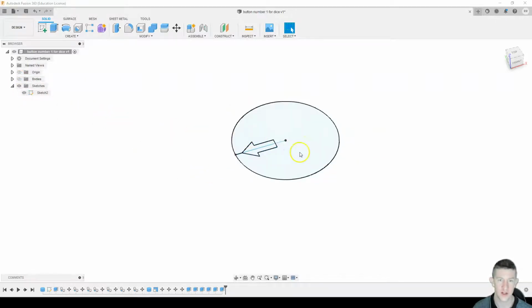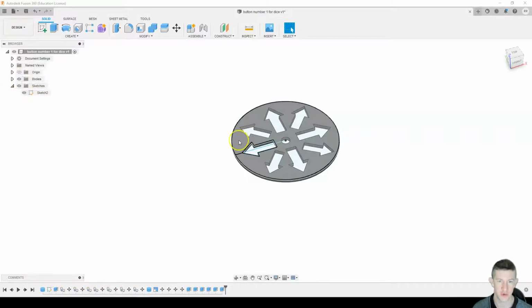By default, once you edit or extrude a sketch, which I'll also talk about, it automatically closes that sketch. But if you're having issues where you're trying to draw on a body and the sketch keeps getting in the way, you may want to just open that and turn off a sketch, and now I can actually highlight the body itself, not the picture that I had before. But generally that shouldn't be an issue. It generally works quite well. It turns itself off. So that's general navigation.